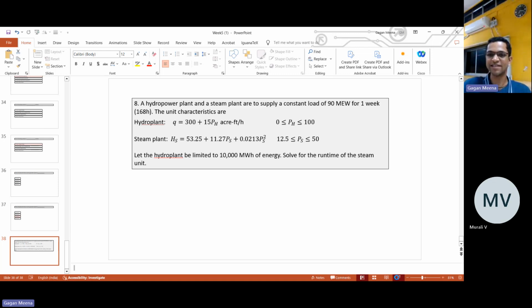They use gas. Gas generation is quite high in the US, and it is costly. They have gas based, oil based, and now batteries are also helping to meet the load, especially during the ramp up and ramp down requirements in the morning peak. When solar is going down and the demand is increasing, at that time the battery is discharged. And they charge when there is excess solar during daytime. The batteries are also helping now.